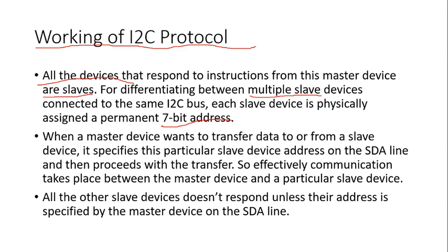So what it is doing is giving the slave device address. When it gives the slave device address, the particular slave is identified, and it will communicate only with that particular slave device. All the other slave devices don't respond unless their address is specified by the master device on the SDA line. First the master has to identify the slave with its address, and only then will it respond to the master.